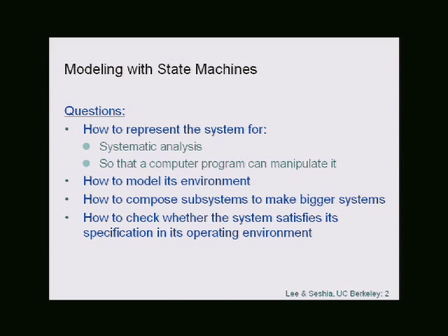State machines are a convenient way to model the system so that an algorithm, a program, can then go and analyze those state machines, say one for the main program, one for the ISR, maybe one to model the hardware that deals with raising interrupts. It combines all these state machines and does analysis which tells you whether there are bugs, and if there are bugs, how things can go wrong. This can be really, really useful. We will study these topics in April: given a bunch of state machines, how you can check whether the combination of those state machines works correctly or not. So that's one reason why state machines are really useful.